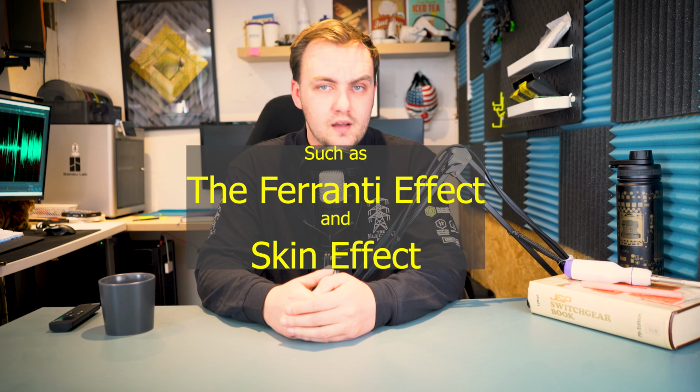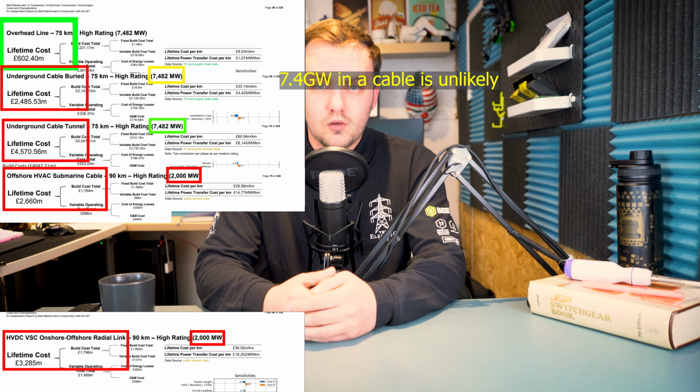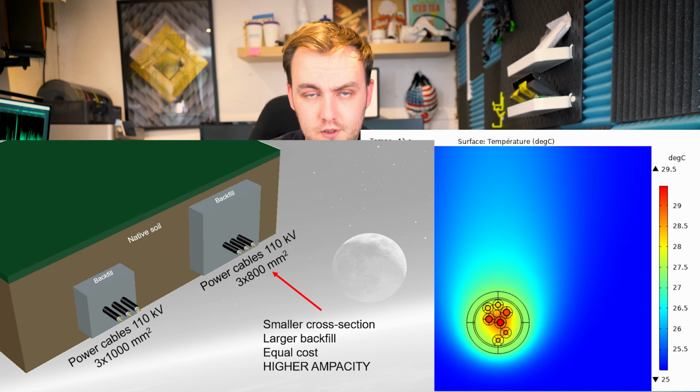And there are other drawbacks and physics behind why cables are generally inferior to overhead lines, except in specific use cases, which I'll cover more in my next video, but for now it's important to know that cables have practical limits. They're more costly over their lifetime, they have stricter limits on current and voltage, and their ampacity, or current carrying capacity, depends heavily on surrounding thermal conditions.